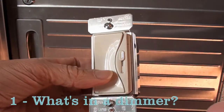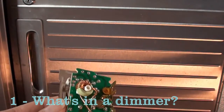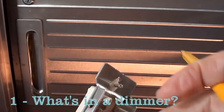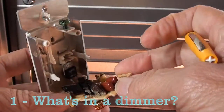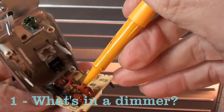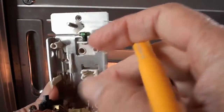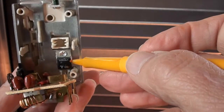So what's in a dimmer switch anyway? I've taken one apart, and we can see the inside is composed of a small circuit board. There's a slider here that sets our brightness. A few components, resistor and capacitor here, which we use to delay turning on the triac. The triac is a solid state device. It's in the bottom of this one. You can see it right here.